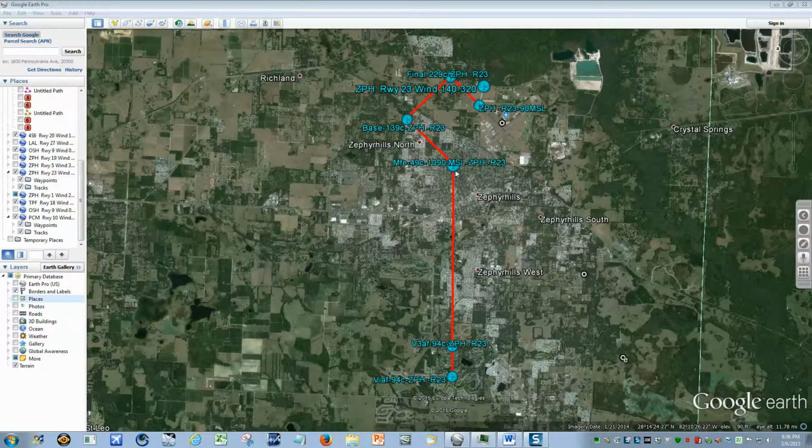We only need to focus on the V3AF waypoint to the MFE waypoint, since our procedures are designed to glide to the runway if at the midfield entry waypoint at traffic pattern altitude.